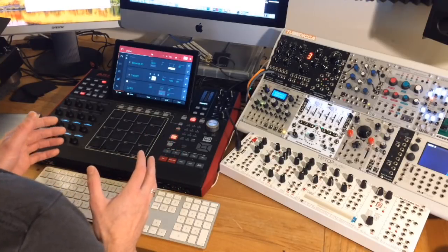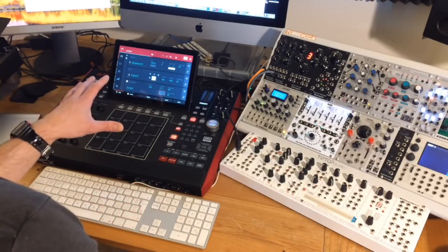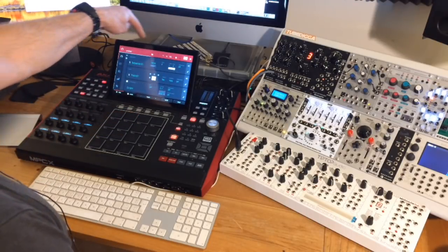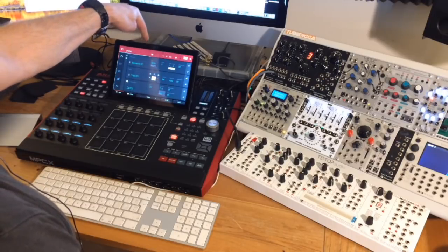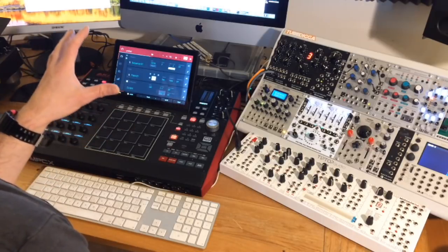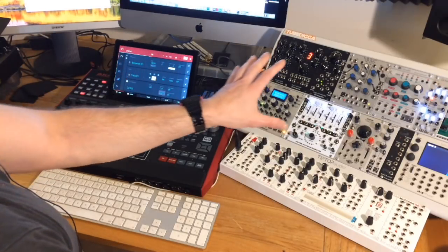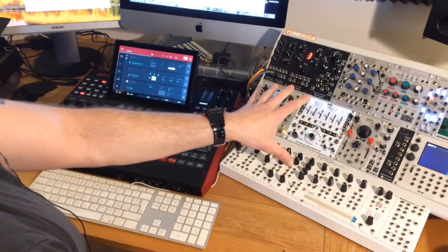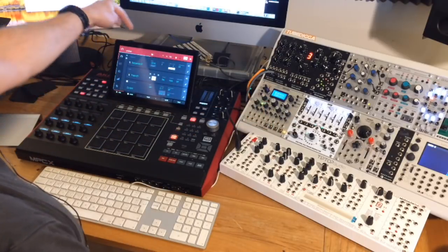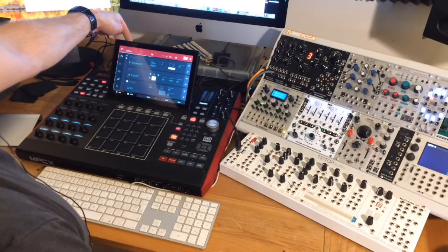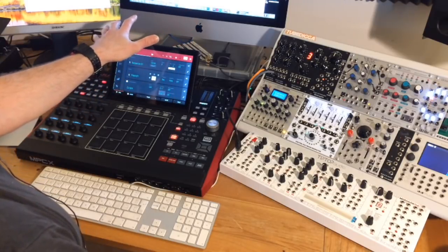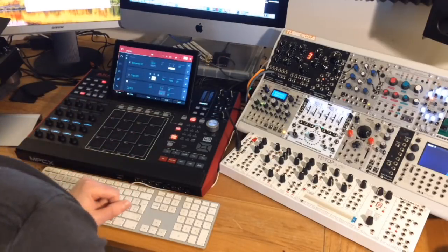So as you may already know, the Akai MPCX has 8 CV outputs. Looking at the front of the MPCX, they go from left to right. So we've got CV output 1, 2, 3, 4, 5, 6, 7, 8, all the way over to the right here. Now for this video, I'm going to be using them in reverse. The reason why is because, as you can see, I've got my modular orientated on the right hand side of my MPCX, so my cables won't stretch all the way over to the first CV ports here. So I'm just going to be using CV port 8, 7, 6 and possibly 5, depending on how I get to that in the video.